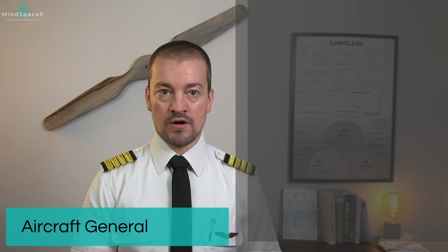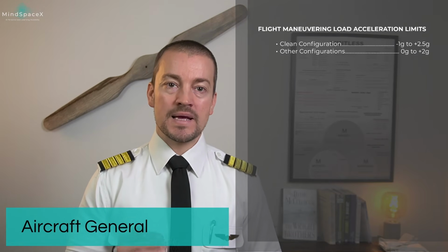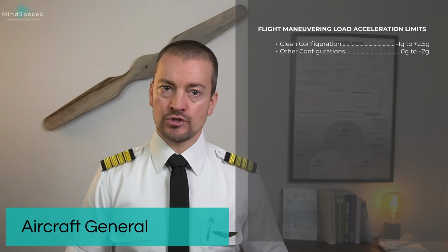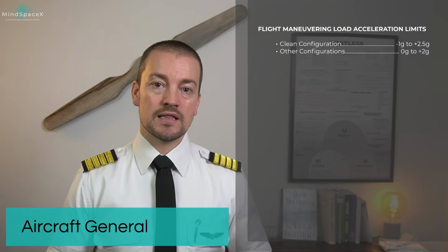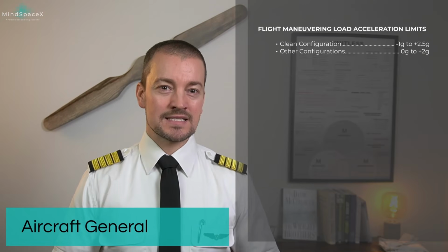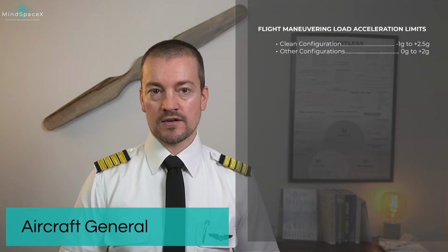We will start with the aircraft general, and we will start with the loading limitations on the aircraft. The load limitation is placed on the aircraft based on structural integrity of the aircraft. We have learned in mass and balance about the structural strength of an aircraft, and we've learned what happens if we exceed the maximum structural capability for the airframe, etc. We talked about design limiting load, design ultimate load, and we talked about safety factor.